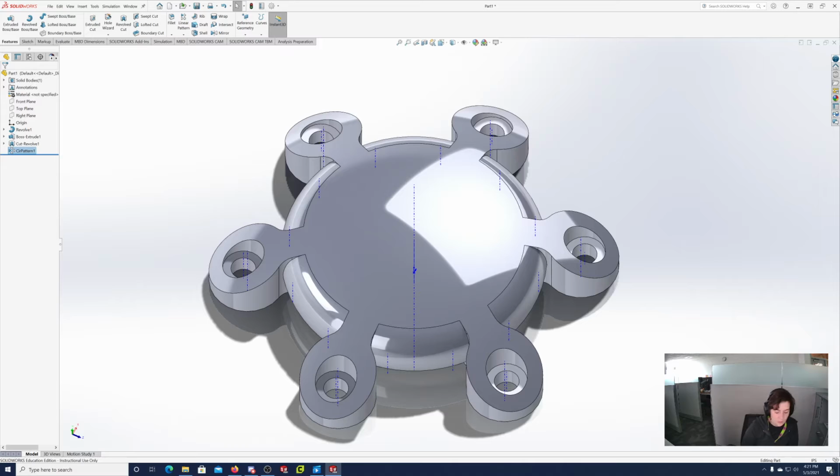So we're going to do that in order to create a sketch to draw these pockets, which are always difficult. There's something funky here in the book with how they have you do it, and I never am really able to get them to work. But we're going to try just so you can see how to make that plane. So on page 728, step 8, we're going to do insert reference geometry. So in your features tab here, again, you're going to go over to reference geometry. You're going to click that little down arrow and you're going to select plane.